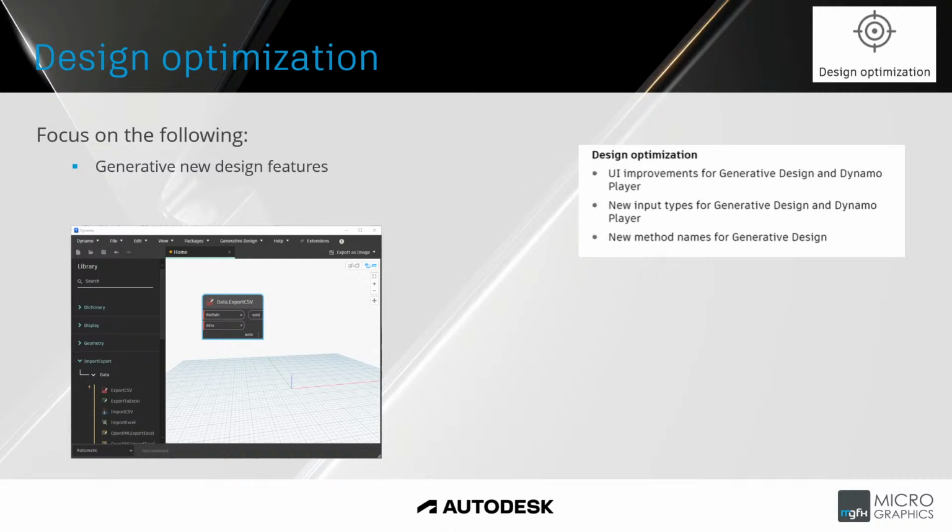Right, then looking at the design optimization, it's basically focused on Dynamo, and Dynamo has been around for a while. It's kind of creating macros within your scenario or your buildings. These macros can be reused. An example: select all the doors that are larger than 900 and change them to 762 size. That sort of macro, you just click a button and it does it in your project, and you can reuse it for each project as you go along. Now they've just improved it.